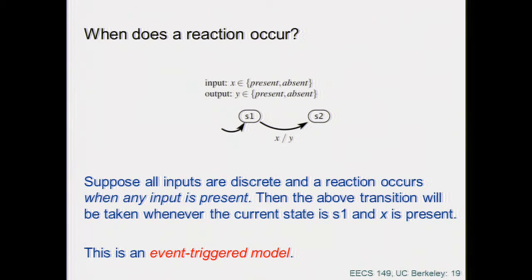That is the difference between event trigger and time trigger. So event trigger is, as I said before, the most intuitive, the fastest reaction that you can dream of. It can lead to problems, like we said before, of a two-button push at the same time. There may be a sequence of commands that come in very fast, one after the other, which are contradictory, and you may enter into very bad behaviors, right? So that's the reason why, in general, time trigger mechanisms are safer. And so when you have a safety critical system, you prefer to use time trigger architectures or protocols or whatever you want to call it. Yes?